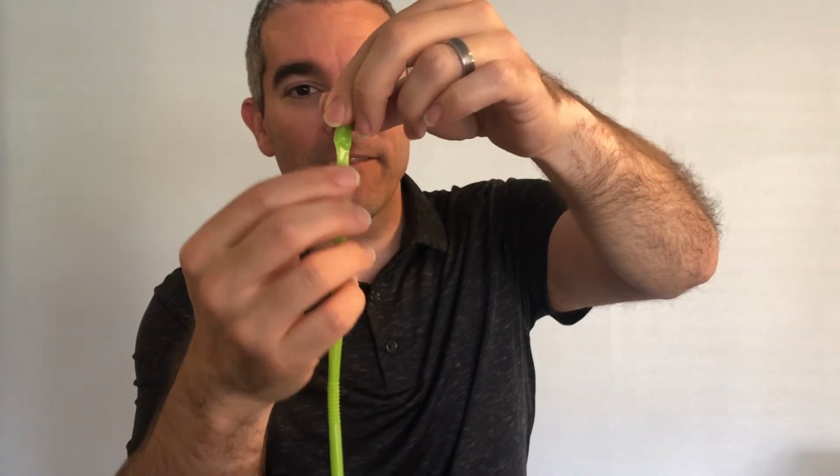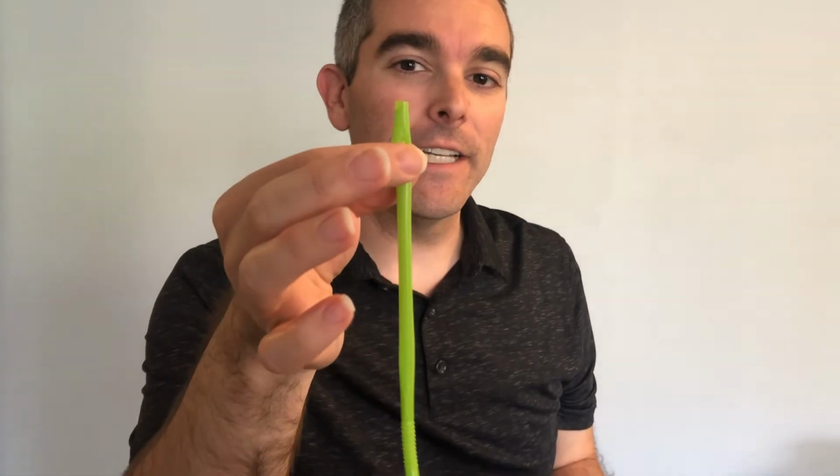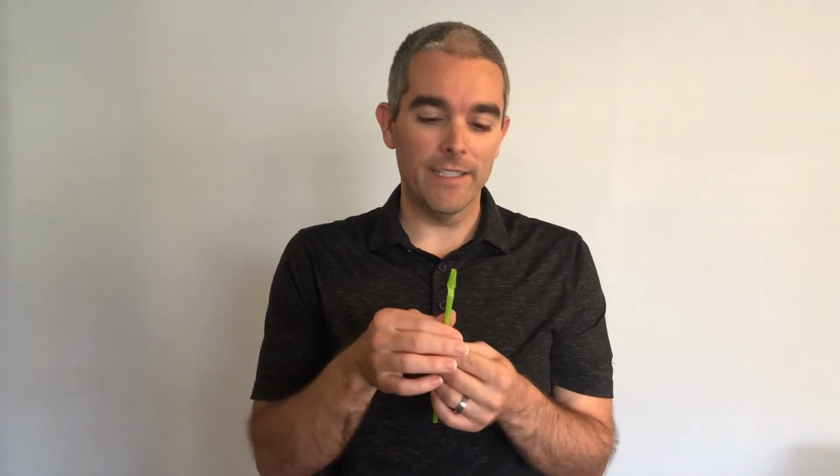If you want to have another experience with yielding, one of the things I used to do when I was a kid, I was one of those kids that after I finished my juice box, I would grab the straw and pull on it. You can go ahead and give that a try to get the straw to yield. So you get something like that. You can see in there the yielding, the reduced cross section. It's fun if you do it really quickly. You can even grab the yielded section and feel that the yielding dissipates heat as one of its energy losses. But you can see that now the straw is permanently deformed.